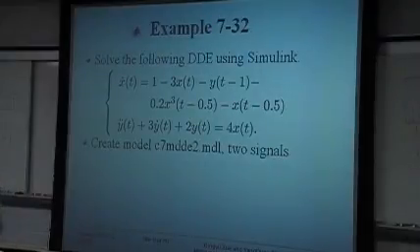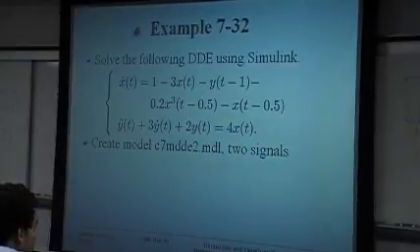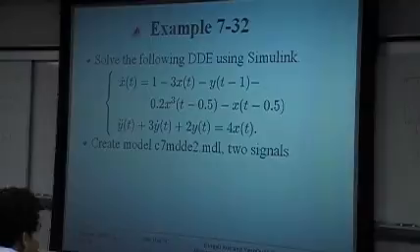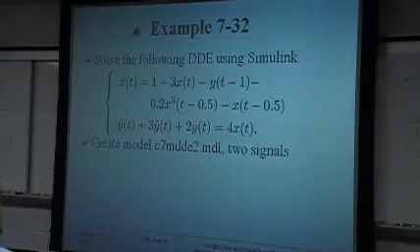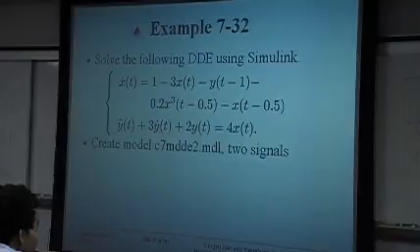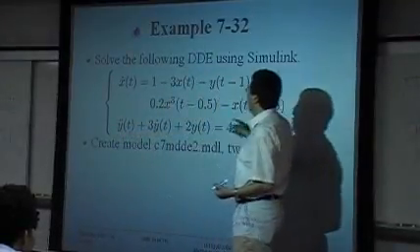If we are trying to solve this kind of delay differential equation, what you need to do again is to define the signals. For instance, you can assign that this one is x at time t, and this one should be x dot at time t. And you can assign this one as y at time t, y dot, and y double dot. I think this one can be easily expressed by a transfer function.